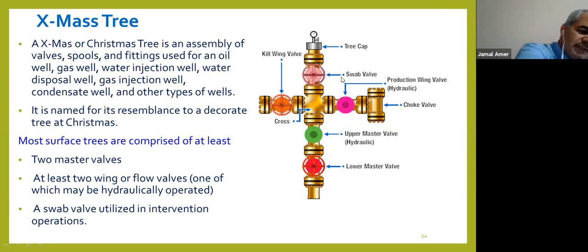In normal cases, this valve should be closed, to avoid damage to this valve, because if it is damaged, again we have a problem when we want to dismantle it to remove the cap for wireline operation.